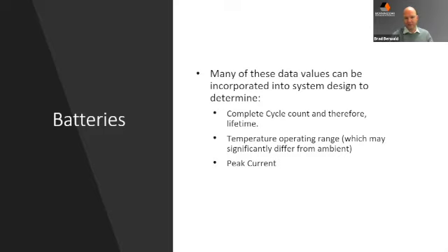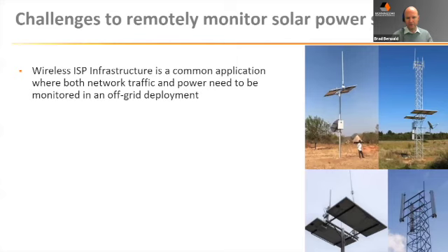than peak currents and surges that you may need a battery to be able to handle if it's going to work in an inverter that could be rated for several kilowatts and might have a 2x surge, up to 6 or 8,000 watts. You have to be sure that that battery is going to be able to handle that current level. So okay, in talking about all these data needs and how you can collect this information and evaluate it,